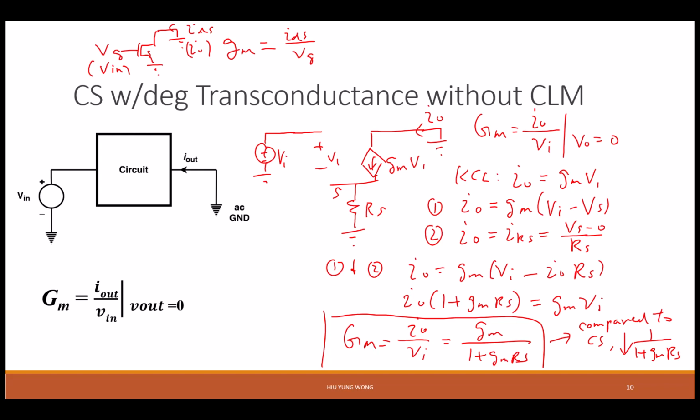How much drain current you get when you change the gate voltage. At that time we did not say this is just Vin, and this is just Iout, because it was a very, very simple circuit, one transistor. But now you can have a very complicated circuit, many transistors, many resistors, and it's still defined as the capital Gm, the transconductance, Iout divided by Vin. Is that okay?